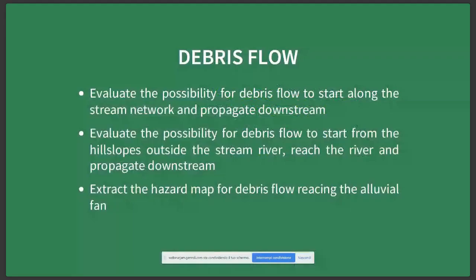But once you have the maximum discharge, you can go on with this discharge and do your elaboration for hazard mapping. If you just have liquid discharge, that's it. But if you have debris flow, like in the mountains where we are, you can also use some other tools to evaluate the solid component of the debris flow.